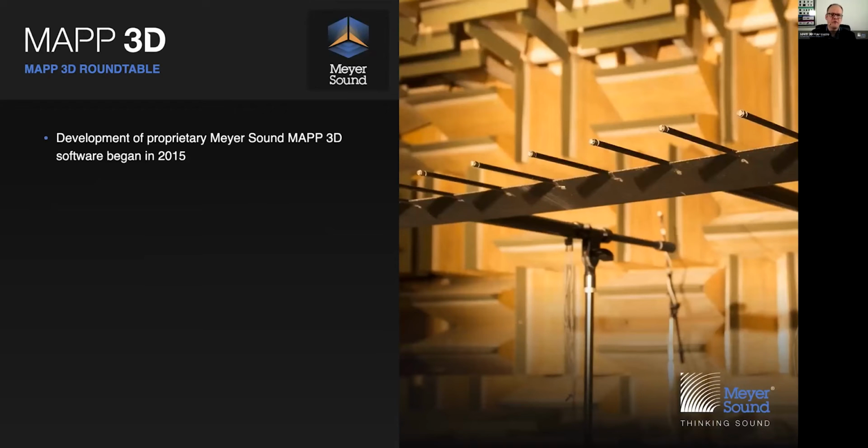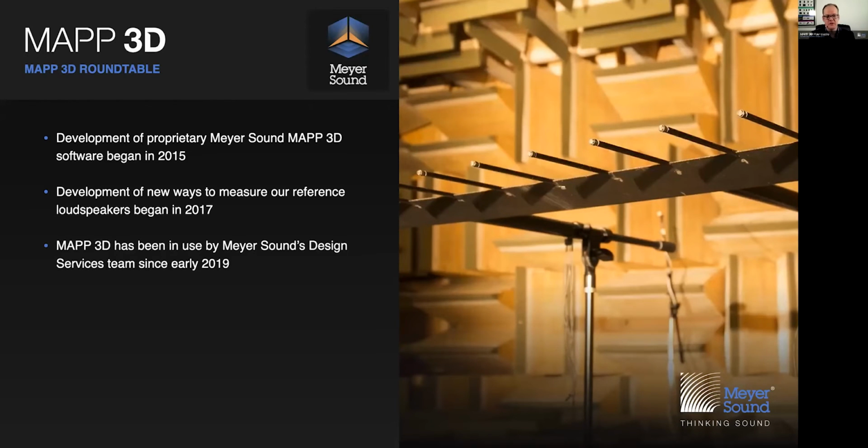So the development of MAPP 3D began in 2015, and in order to do so in an expedient way, we also had to develop new ways to measure our loudspeakers, starting with the microphone array that you see to the right. So we no longer have a single microphone with a loudspeaker that is orbiting and pivoting, we now have an array of microphones which contains 10 microphones rather than one, and that speeds up the process of scanning by a factor of 10, because every time we rotate the loudspeaker, we get 10 pieces of information rather than one piece of information. And internally, MAPP 3D has been used by our design services team ever since early 2019.